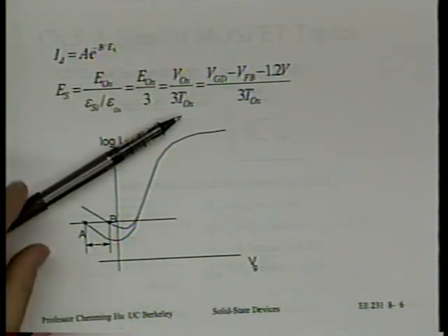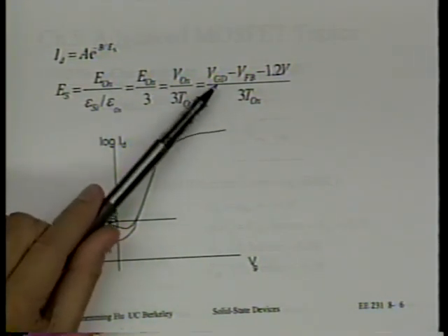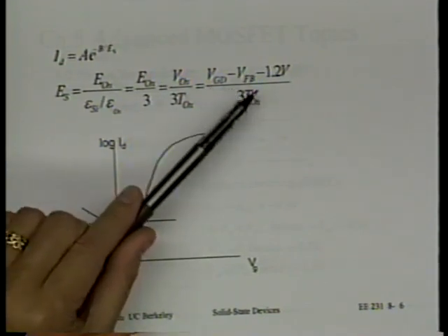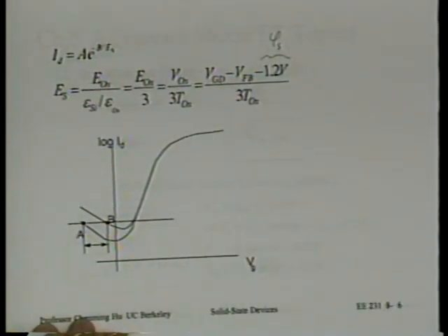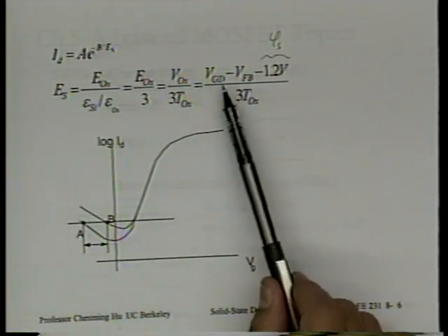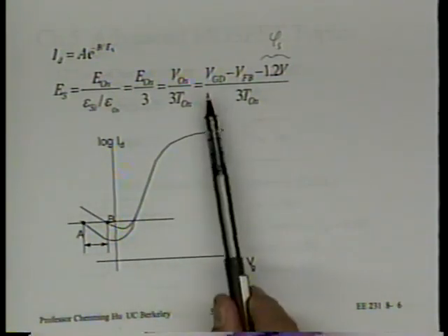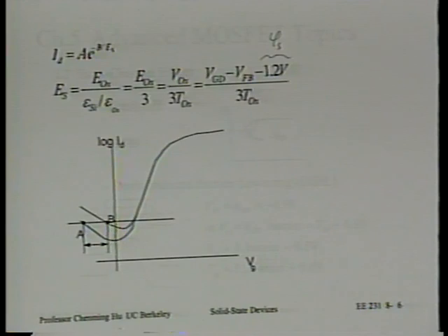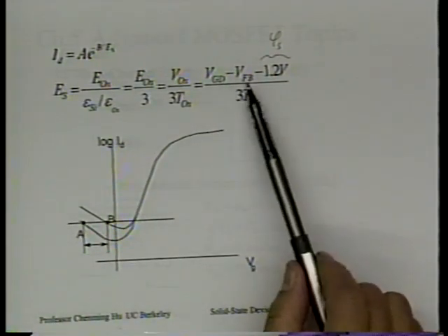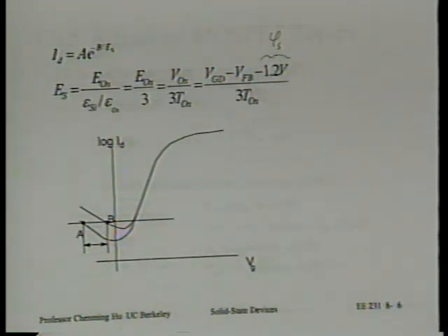Well, the voltage in the oxide, we know, is always equal to VGD minus VFB minus phi s, the band bending. Right? We're using the same old equation in another new problem now. Instead of calling that VGB, I guess we call it VGD because our substrate this time is the drain. So VGD minus VFB minus phi s. The problem is always not knowing what phi s is.